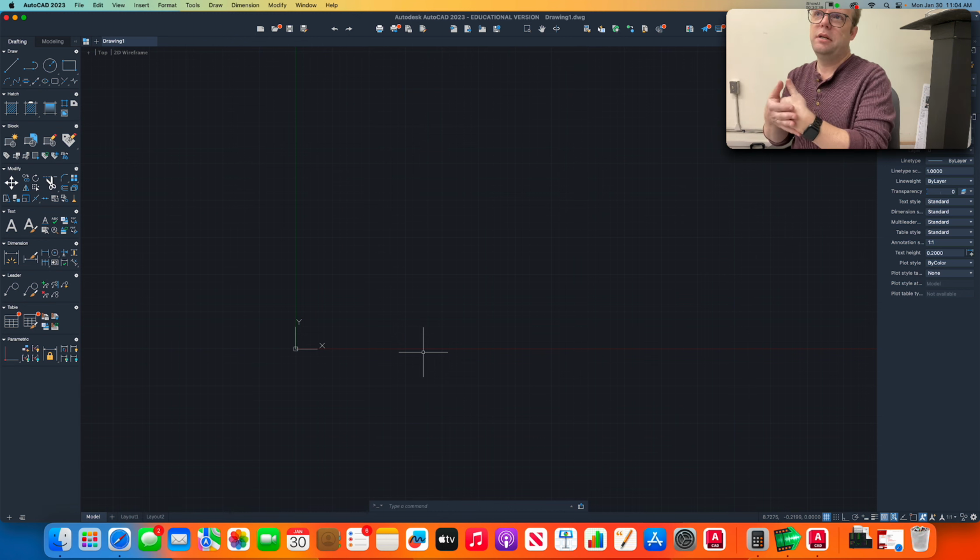So very rarely in our world does that scale piece matter, but every once in a while it does, and if it does, then yes, you would need to say, hey, for every half inch on this piece of paper, that represents a foot in real life, okay? But very rarely in our world does that matter. So you get to decide what the units mean, okay? And let me show you what the options are. Type the word units, U-N-I-T-S, and hit enter.